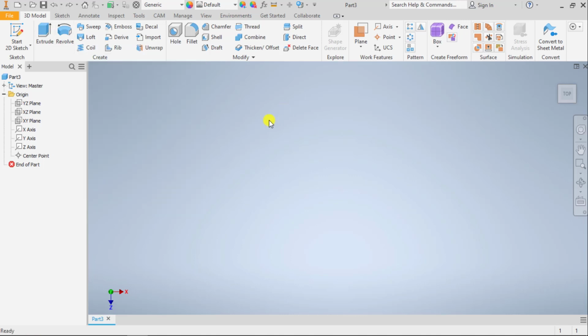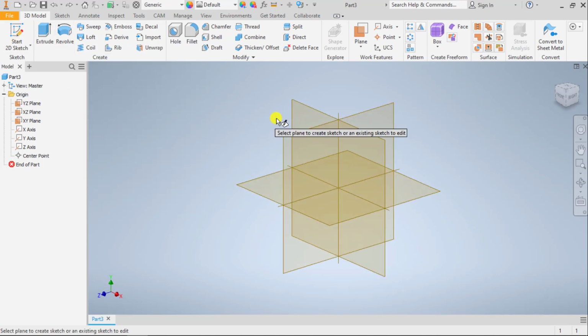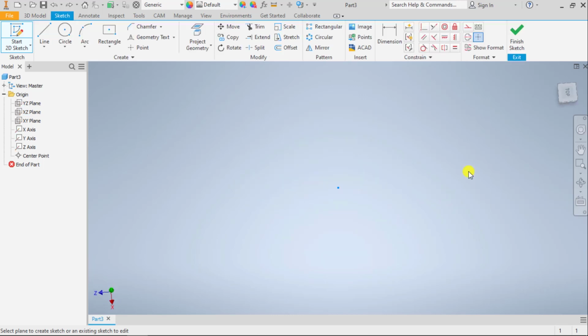So what we need to do first is make a sketch, and we're going to make a sketch on our top work plane. Again, I've said this before, but please pay attention to make sure that the word top reads correctly. Top view sketches in Inventor, for some reason, do not read correctly. They rotate 90 degrees. So we're going to go ahead and rotate our view cube 90 degrees. The next step is to project all three planes. Remember, your part is going to look like this. So we expand origin, click all three planes until we get our plus sign. Good habit to be in.